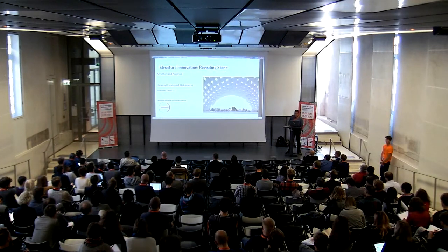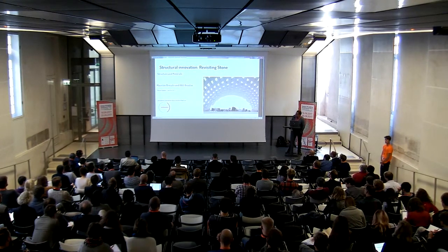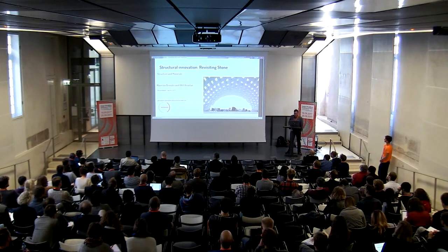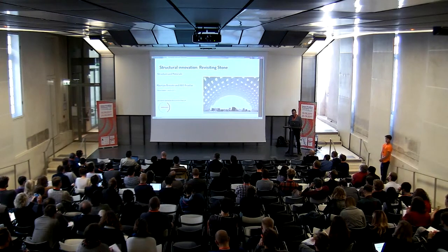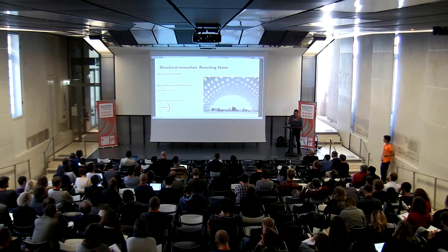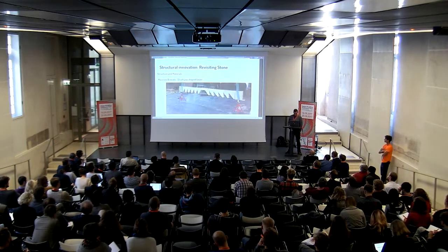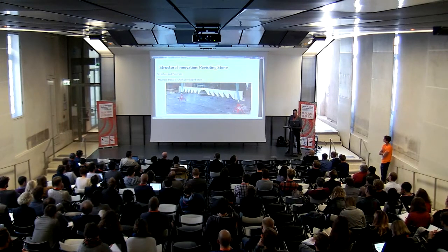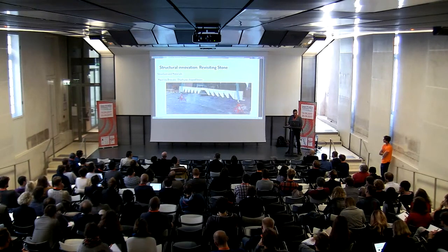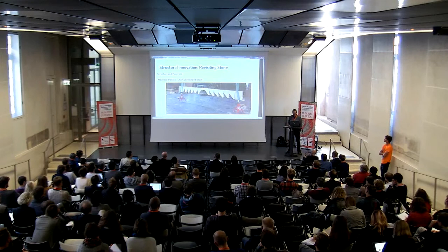Here is his recent construction made in Jericho with the architect Anastas in Palestine. It's a wonderful structure reusing the Abeille system with a modern way to cut the stones and also to glue them. Another example from Maurizio Brocato he called the shark jaw shaped beam. If you are used to structural mechanics, then you can obviously see that the stone is taking the shear force and the compression force. And of course, the rebar is still there to take the tensile forces.